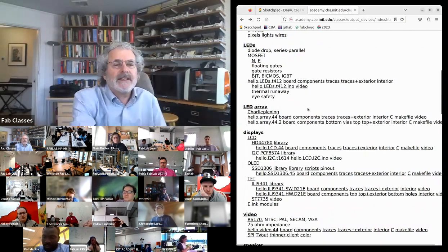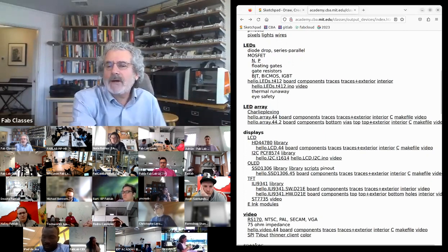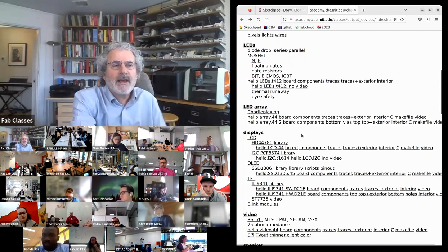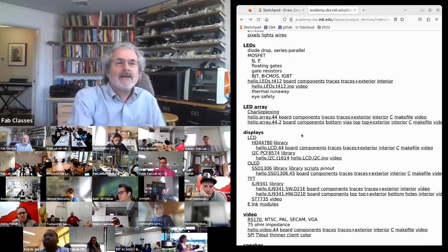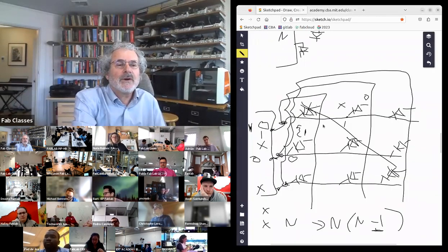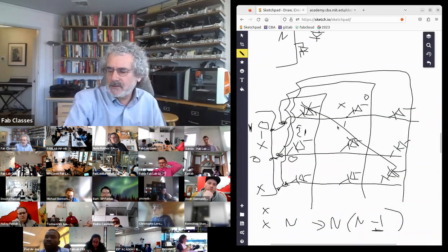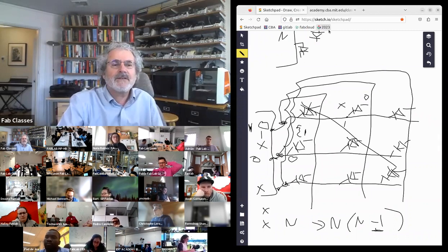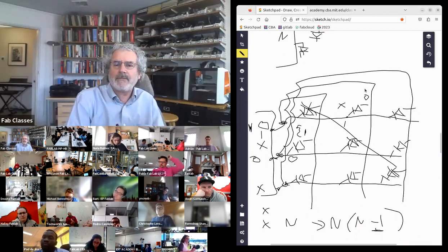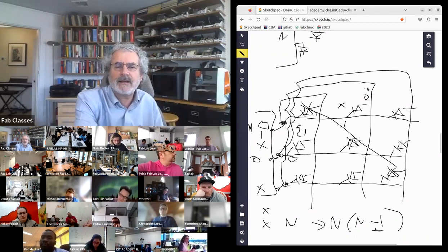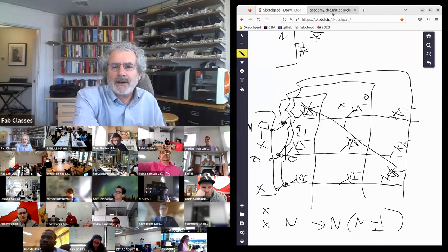But Charlieplexing lets you control n times (n minus 1). And so there's a question, Dorian. There are all sorts of use cases for this where you can have diodes, then you can have lights or sensors or switches, to make n things going to n squared things.